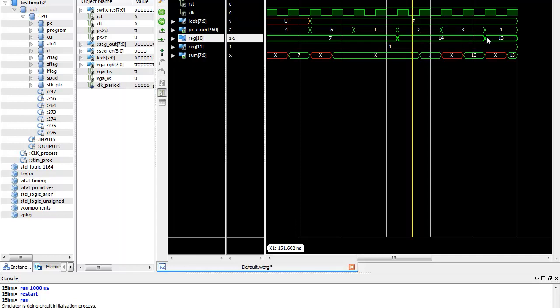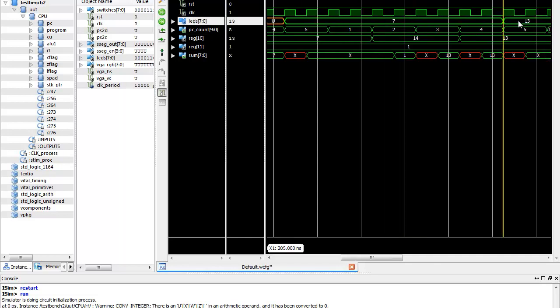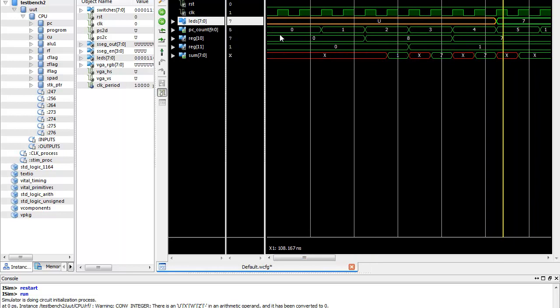And so forth and so on. Once we start here from the in instruction, we only need 8 cycles later, so let's see, run, in order to get the output of 14 minus 1 onto the LEDs. There it is right there. That only took 8 cycles instead of 10, because remember we didn't have to execute instruction 0 like we did the very first time around.